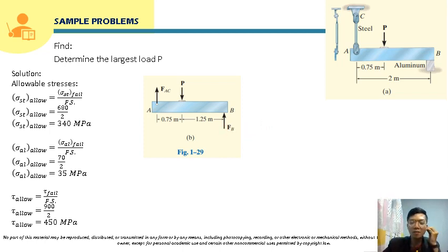Okay, so in order for us to solve this free body diagram, as you can see here, this is a parallel force system, right? As you've learned in your statics of rigid bodies or engineering mechanics, we can only generate two equations here since this is a parallel force system. It can be one summation of forces vertical or horizontal, but in this case, these are vertical forces. So one summation of forces vertical and one summation of moment at any point. Or you can also use two summations of moments. In this case, we are going to use one summation of moment.